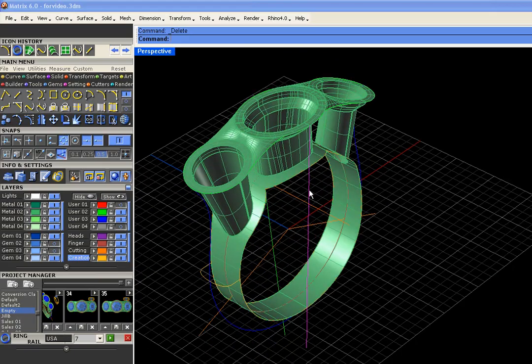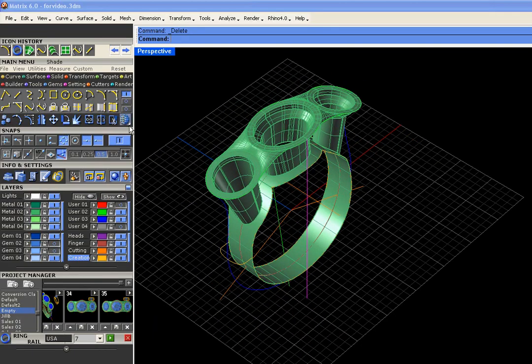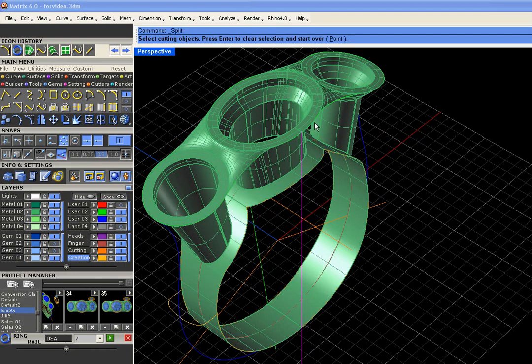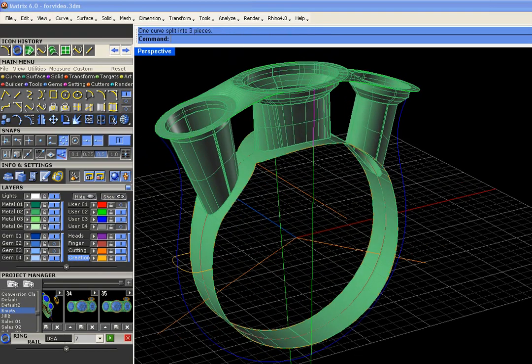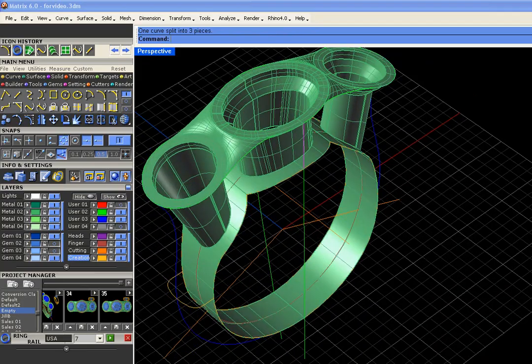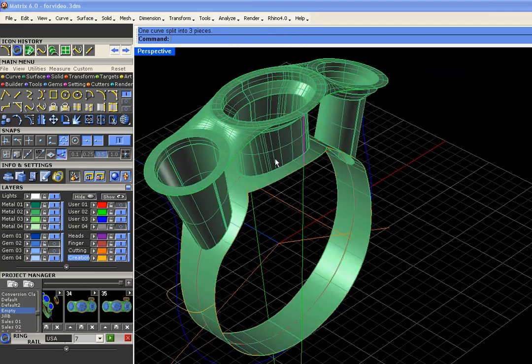We know that this guy touches because all the curves were made from him. So we're going to run a split. And again, if you're being really anal like me, duplicate it in place first, grab one copy and stick it on gray. Now, split and split him with the curve and the curve. And you're going to be left with a little profile. There's a guy. Okay.